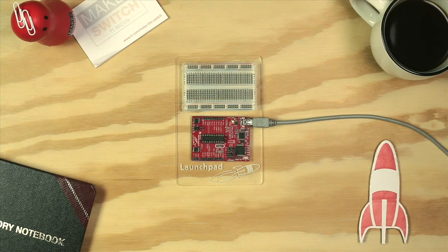Hello! In this tutorial, we're going to show you how to send data from a personal computer to the MSP430 G2 LaunchPad to control the brightness of an LED using Energia and the Processing IDE. The data is sent in individual bytes, each of which ranges in value from 0 to 255. The LaunchPad reads these bytes and uses them to set the brightness of the LED.